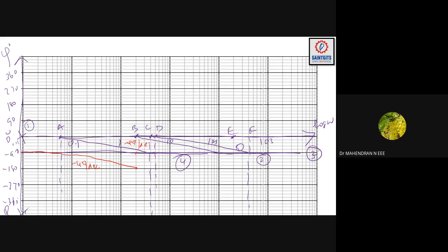So it means that 180 plus 90, minus 90 degree per decade from C to D. Okay, once again, 90 degree, minus 90 per decade from D to E, it will be 45. So this is minus 45 here, and I can say this will be drawn like this.